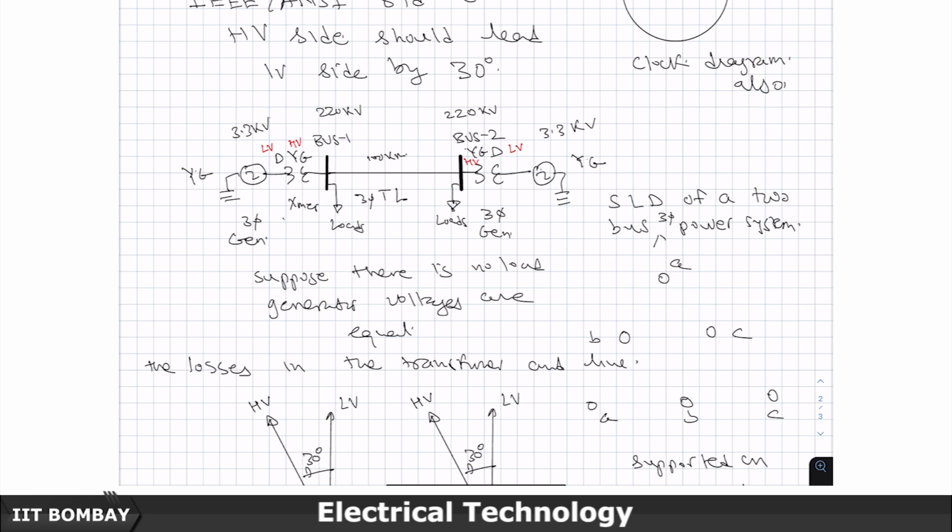So, winds, cyclones, faults, even heat, temperature, sagging of conductors, a tree touching a conductor, snakes or birds creating short circuits between multiple phases, all such things will create faults, which are large currents that can damage the equipment because of the heat and the forces generated in it.